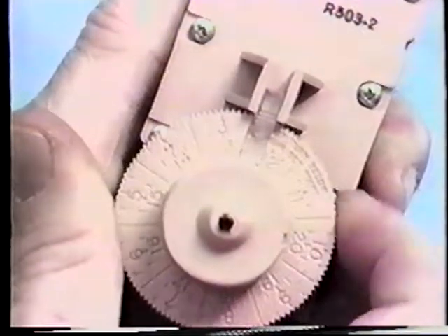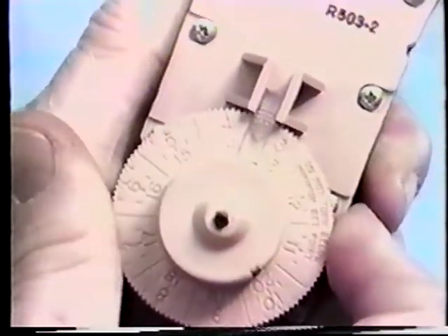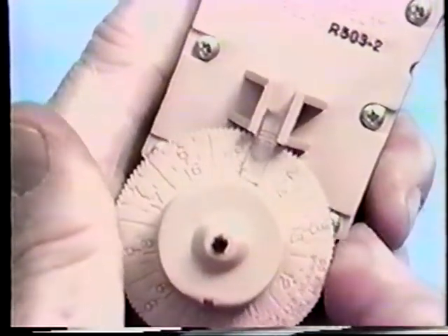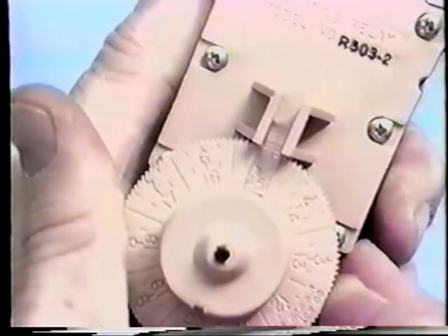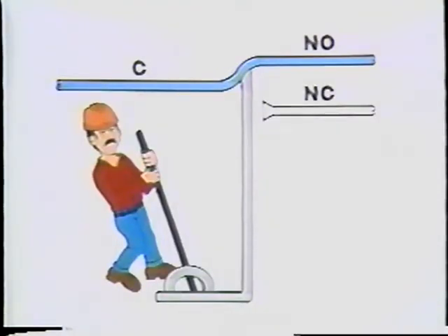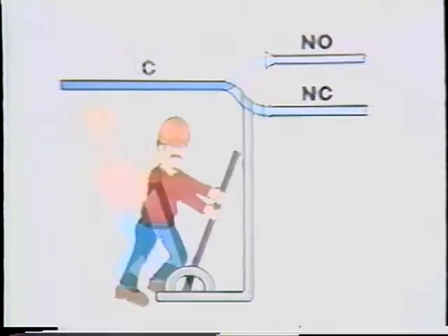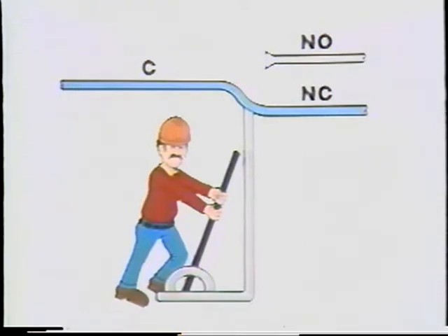This is accomplished by changing the set point adjustment to a pressure setting between 3 and 20 PSIG. When the pressure at the signal port reaches and exceeds this setting, the relay switches. This closes and blocks the normally open port and opens the normally closed port to the common port.